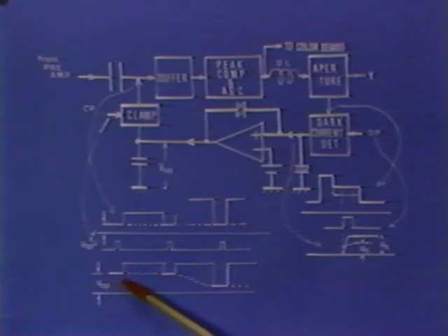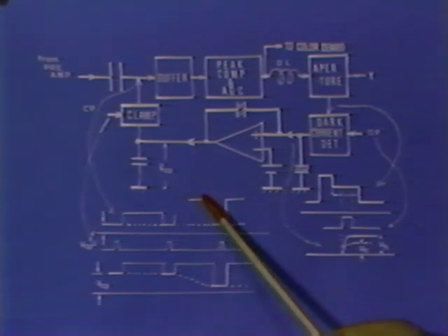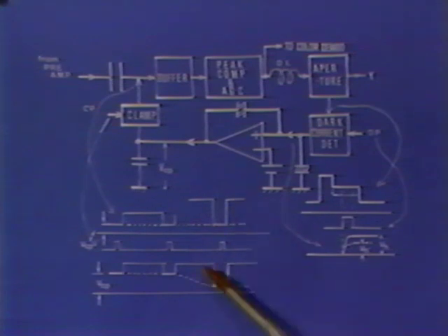For this, the clamp voltage goes down, and so does the DC reproduction level of the color multiplex signal like this. Therefore, the upward black level is pushed down to be constant. In other words, the dark current fluctuation is cancelled. This is it about the principle of the dark current compensator.